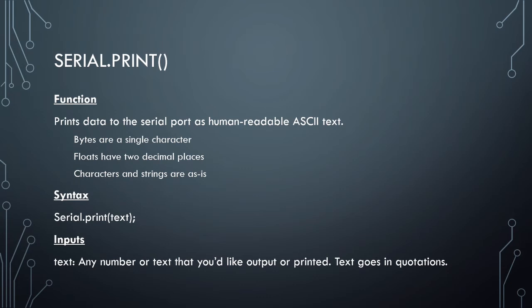So the way that we write our serial print command is the word serial, and then we have a little dot in here. So you'll remember digital write was kind of all smushed together. Pin mode is 2 words kind of smushed together. This one, they're separated by a little period in the middle. So we have serial. Make sure that you are spelling it S-E-R-I-A-L, not C-E-R-E-A-L, as in a bowl of cereal. There's a difference. So we have serial.print, and then as usual we have our 2 parentheses ending in a semicolon,